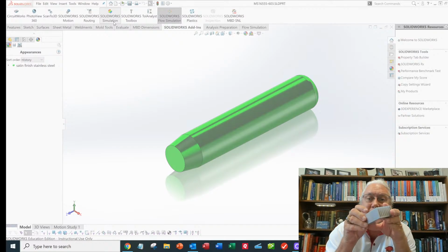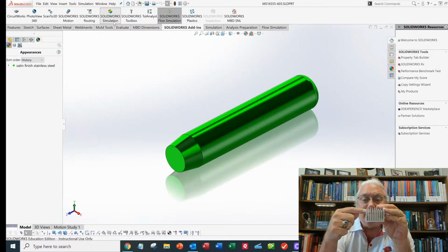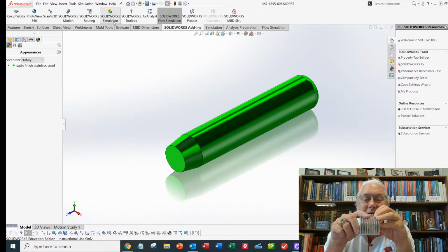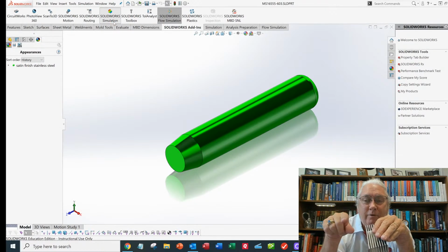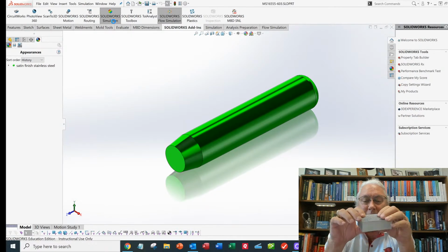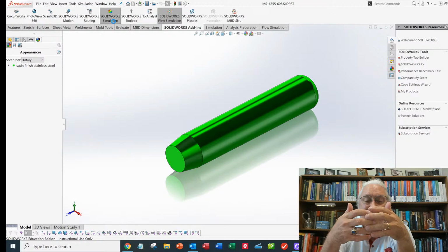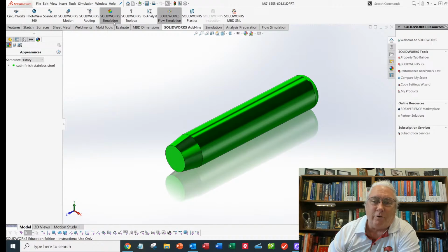And so like this heat sink, the strength of the material is the same in all directions. So that's isotropic. For things like wood, it's not isotropic, so you can't use the same modeling techniques. You can use the same modeling techniques, but you need a different solver to handle the different structural component material properties in different directions.